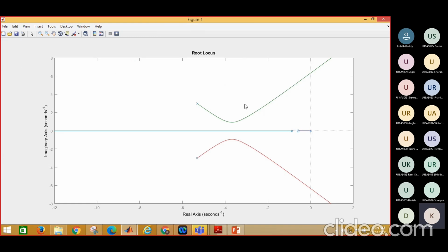These were root locus branches for the outer loop system. You will see here, this is the outer loop poles. When the gain is 0, it has a damping of 0.871. Yes, if you see here, in the previous case, I selected my gain value as 2.5.